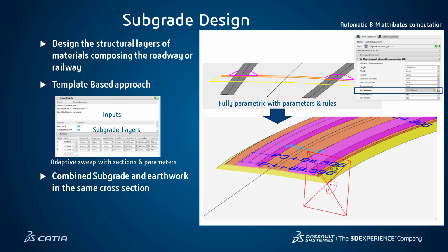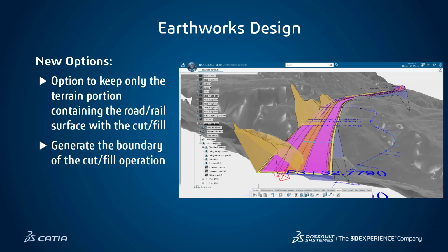Now, Civil Engineer. New to Civil Engineer in 20X, there's been enhancements to subgrade design that come from templates. These are templates that are loaded into the database and then accessed through this dialog box, where the parameters that drive the template are exposed in the dialog box and can be manipulated. So here you see with the Earthworks design, those templates